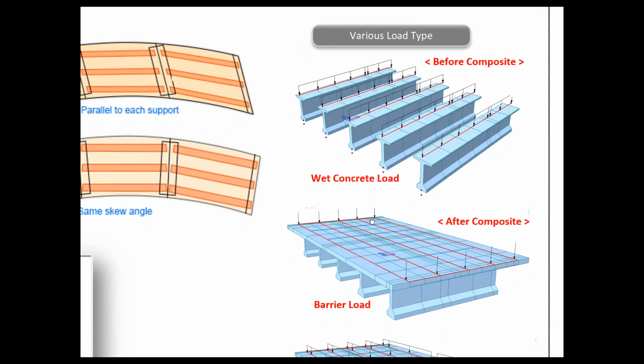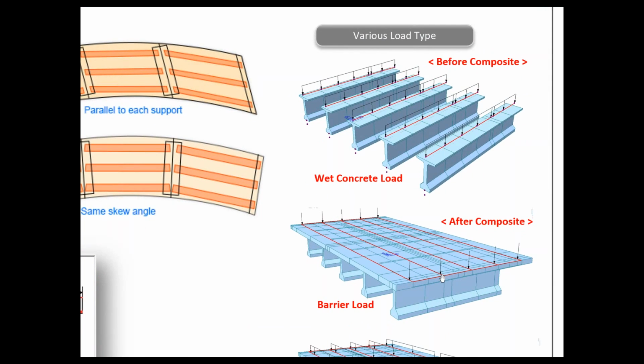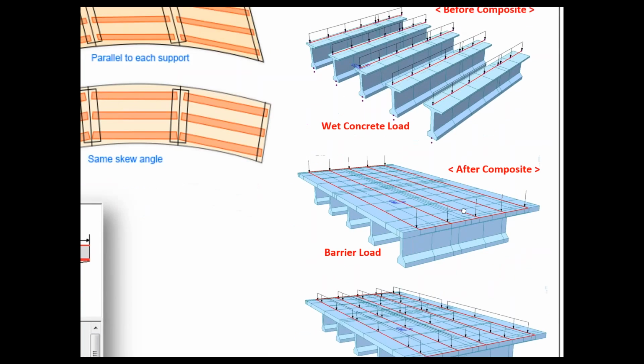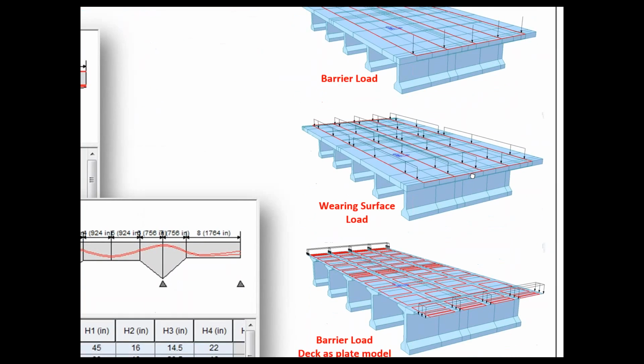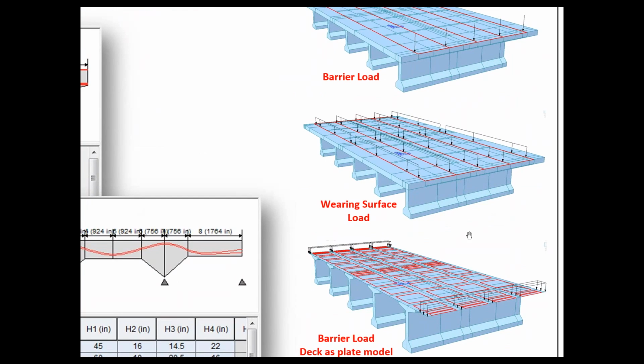And when you define your loadings, dead load, and various superimposed dead load, it's going to apply them in the most proper format like this. So if you within Civil or in any other program, if you were ever curious, like, oh, I punched in this loading, but how is it being applied? You can actually visualize it within your model of Midas Civil, just like this.